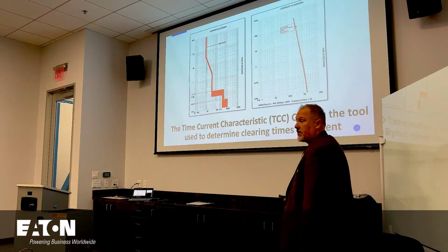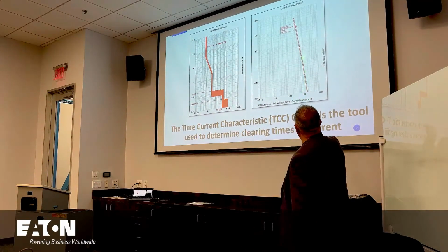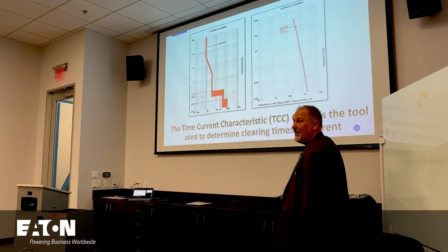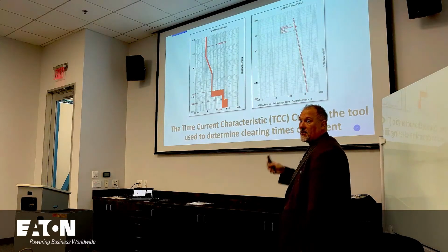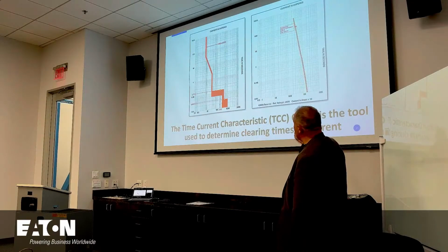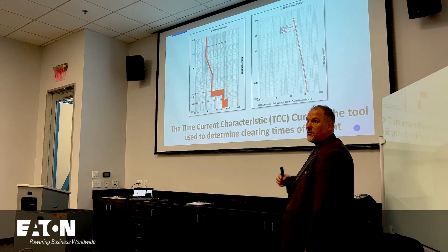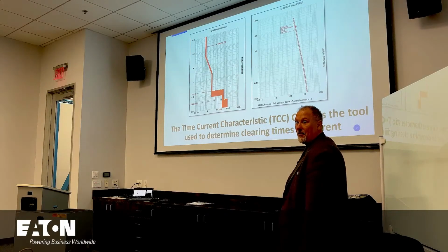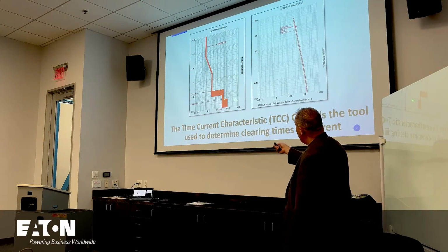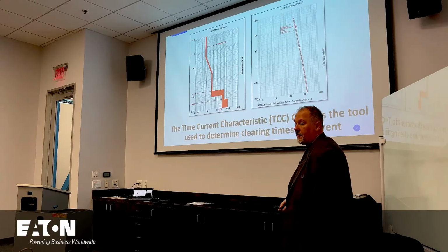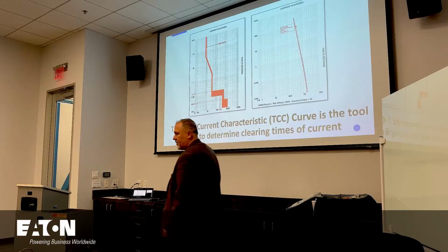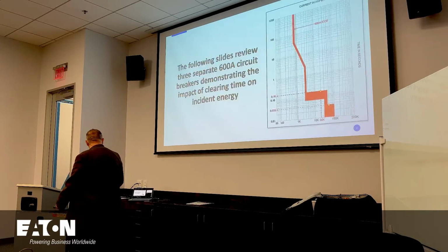And the fuse, same way. And in fact, you don't want to be on this side of the fuse, right? It's the lower currents on the fuses, and they have a much higher, faster rate of rise. This is like falling off a steep roof as opposed to a flat roof. I'd rather fall off a flat roof. And that's your flat roof. But you want to be in the current limiting region of a fuse. You can't get anything that will work faster and more efficiently than that overcurrent device.